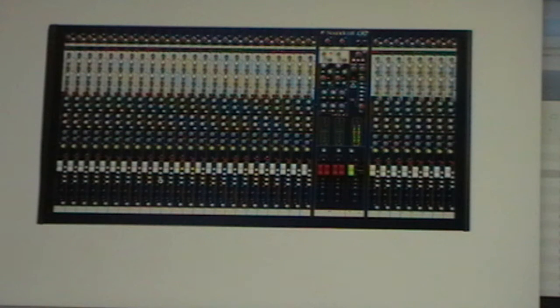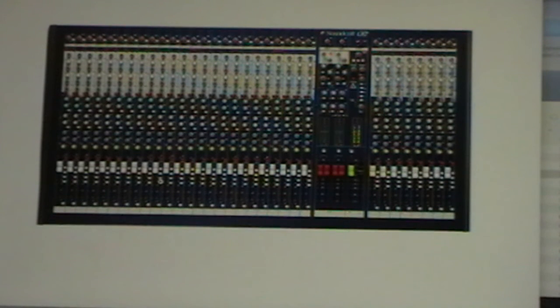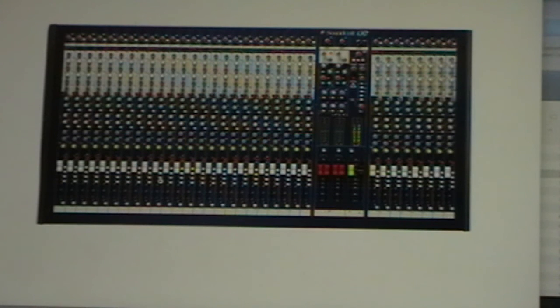So an example will be your graphic equalizers, which will have 1/3 octave faders, and you can boost or cut any frequencies on it, which provides sufficient capability for system equalization. And you've also got your parametric equalizers that have been popular since the 1970s in recording studios, and they can be boosted or cut within individual sections.